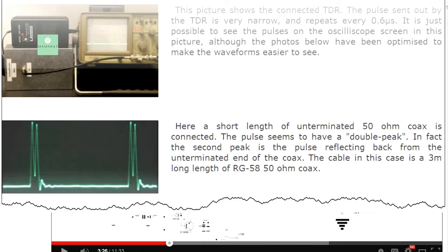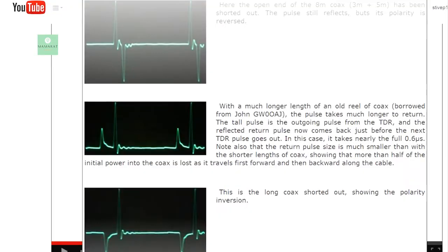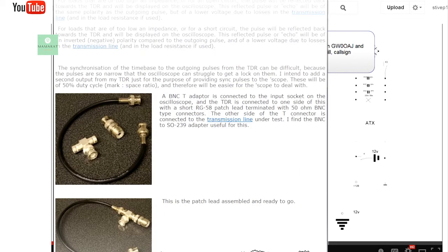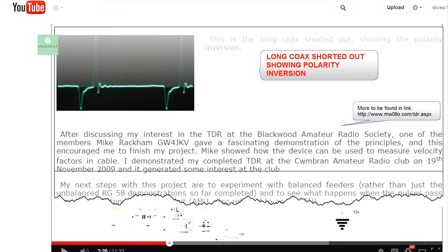By looking at the waveform on your TDR, you look at the echo pulse: is it positive going or negative going, tells you is the impedance at the end higher or lower, and the wave shape tells you whether or not there's any capacitance there. So you got a lot of information on that oscilloscope screen of a time domain reflectometer that uses this phenomenon. So I know that this is the beginning of a question, and give us the rest of the question, Wes.